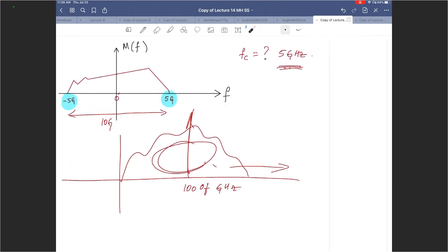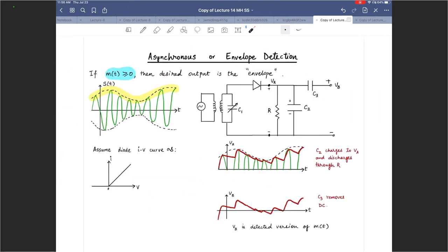So over here, I'm just using an envelope detector, which is based on a diode. And what does the diode do? That is essentially going to clip off all the negative regions, right? So if I take a look at the voltage-current characteristic of an ideal diode here, as I increase the voltage, my current is increasing. But if my voltage is negative, I don't have anything going through.